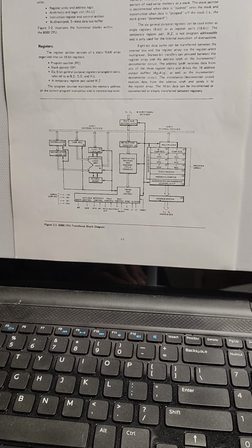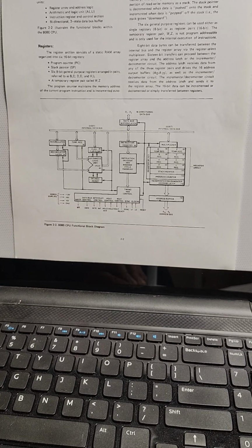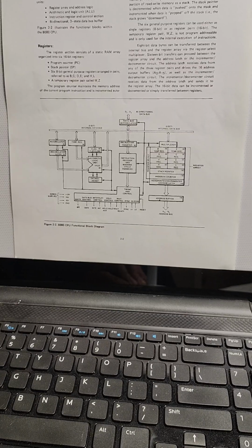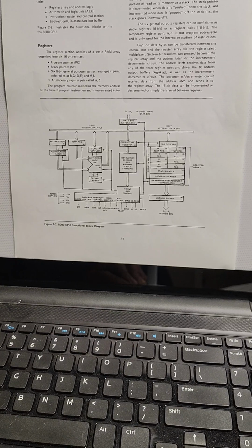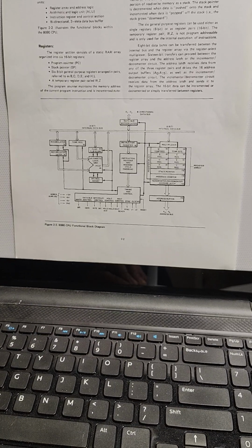The 8080 uses assembly language as its low level, but it's relatively powerful for its time. It can do conditional and unconditional branching, looping constructs using decrement and jump, memory indirect address via the HL register pair, and subroutine call stack management.